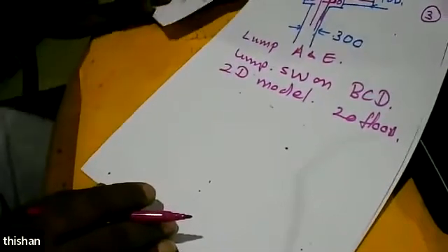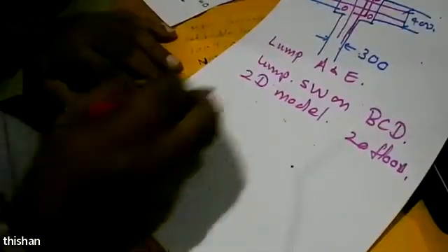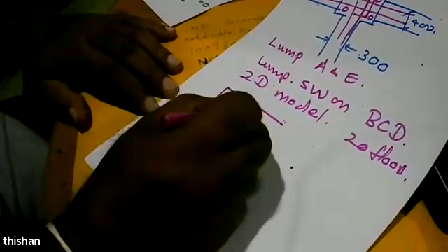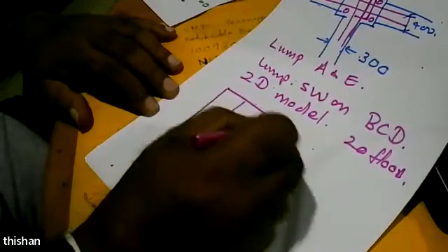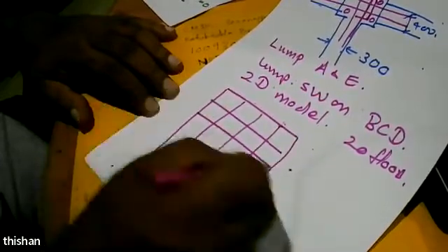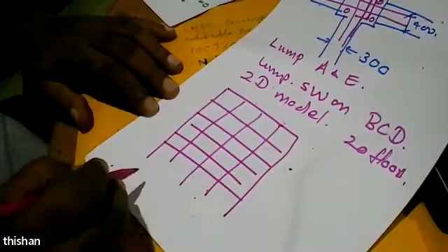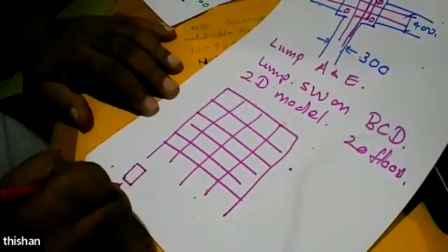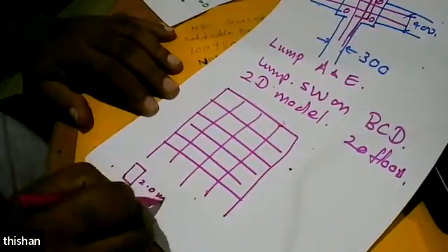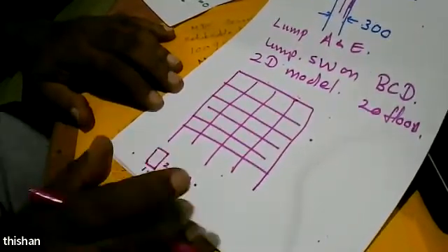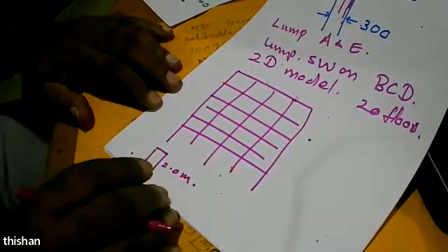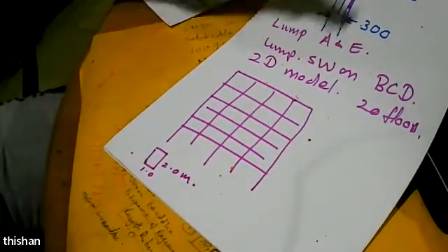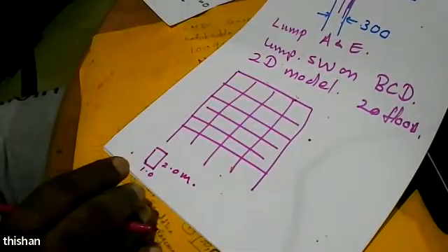How to create a 2D model of the structure? Now we lump these four. We get this. And if the column size is 1 meter, now you get 1 meter by 2 meters. You can't extend it the other way because then you are increasing the stiffness unnecessarily. You have done it if you have just put 2 columns together.